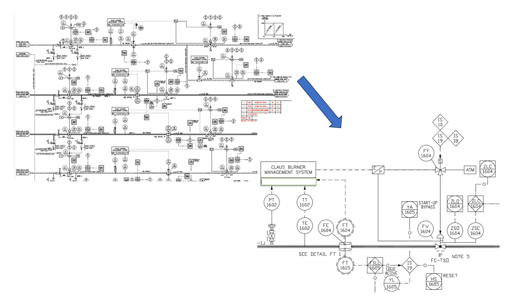So this is a particular example where you can see a whole P&ID, and within that P&ID I have taken a small section to give you a practical overview. You can see here it is written PT, P at the initial, right? So PT means pressure transmitter. Here you can see TE. TE means temperature element. TT, temperature transmitter. FE, flow element. FT, flow transmitter.